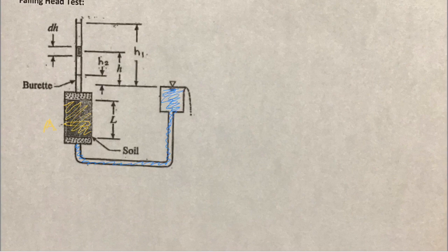Whatever overflows, in the constant head test we actually kept track of it, but in this test we don't have to. Then we saturate the soil specimen, and then we attach a burette or a standpipe